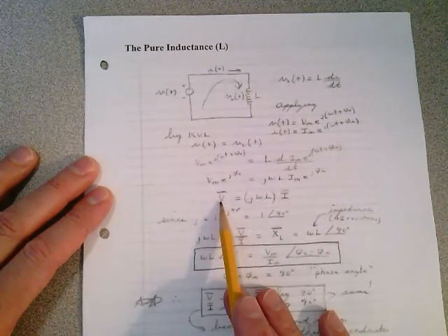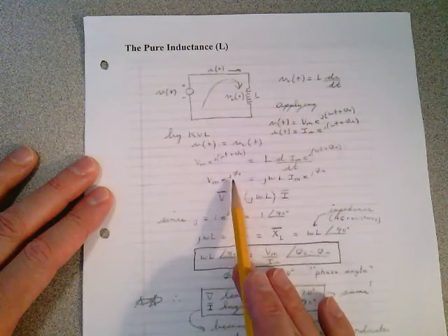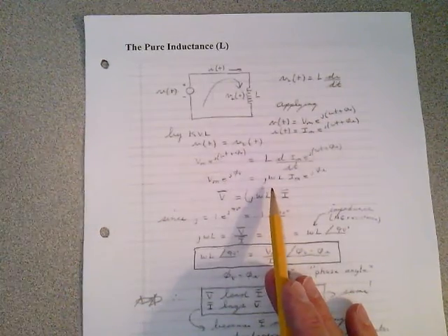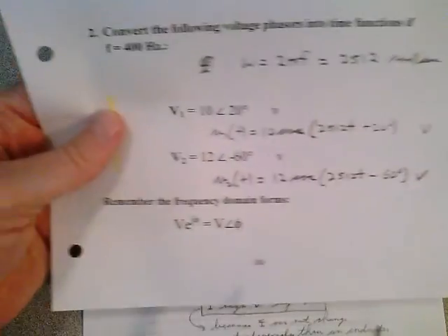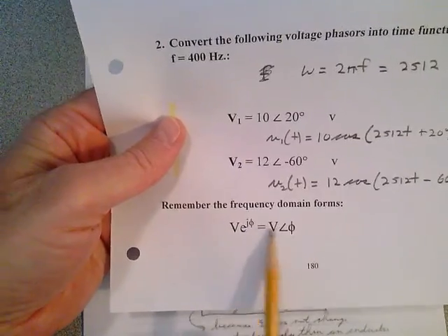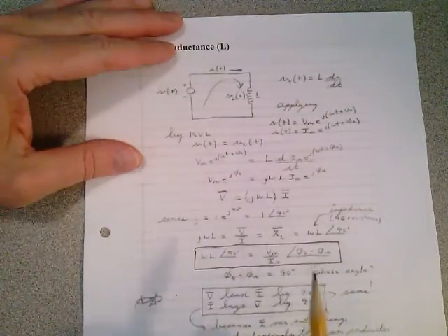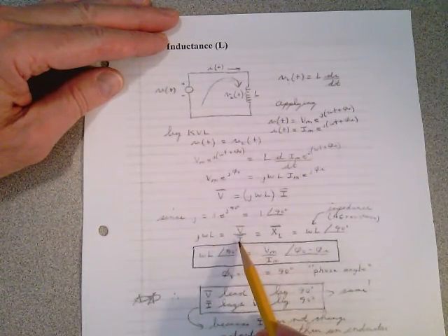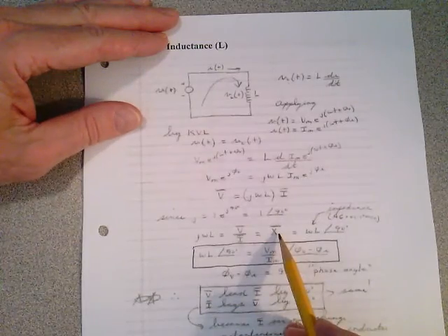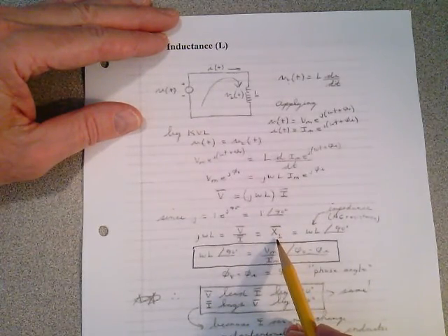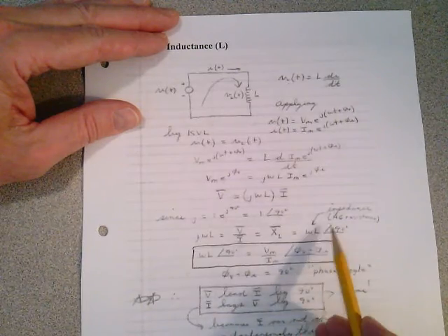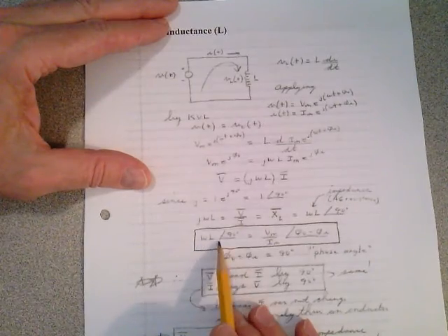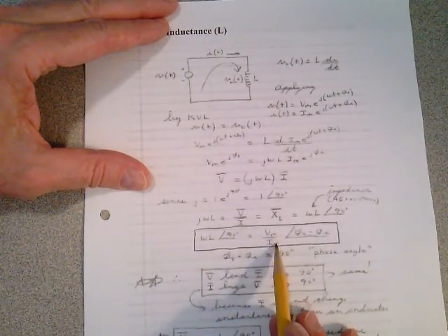You can see that the voltage in the phasor form, once you drop the exponential forms out, using this technique I showed you here, remember the frequency domain forms, you're going to end up with j omega L is equal to V over I, which is equal to something called the inductive reactance. Well, look up here. It has to be equal to omega L at an angle of 90 degrees. So omega L at an angle of 90 degrees has to equal V max over I max times the angle of